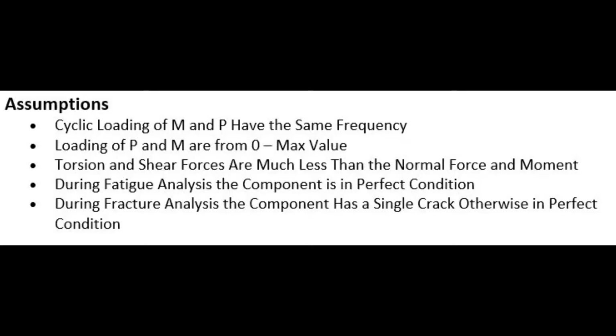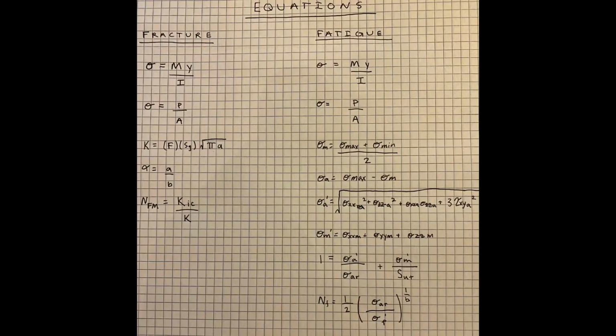Similarly, assumptions were made in order to analyze fatigue failure based on what we are equipped to solve. Although we know our loading scenario will not be perfectly repeated over and over, we assumed that over the course of many cycles, this loading is essentially an average, and as such, treated it as if it was replicated for every cycle. We also assumed that the combined loading acts in the same frequency and phase with each other due to the nature of the use of a ski pole. Here are the equations that we use for both our static failure and our fatigue failure.